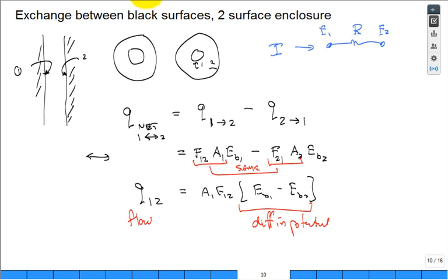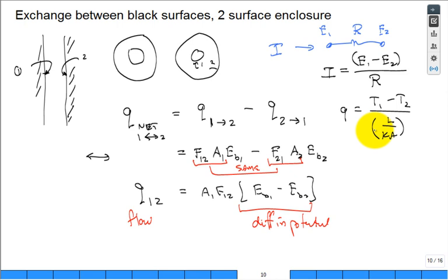And Ohm's law had that the flow of current is equal to the difference in what drives the flow of electric current, which is the EMF, the electromotive force measured in volts, divided by the resistance, the electrical resistance. And we did the same thing when it came to heat transfer through a slab, didn't we? We had Q is equal to T1 minus T2 divided by the resistance L over KA for a slab. All that's good little review.